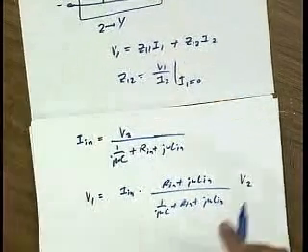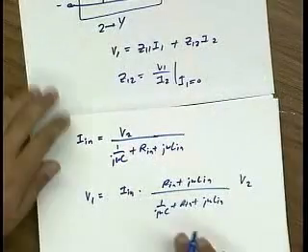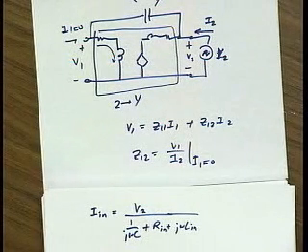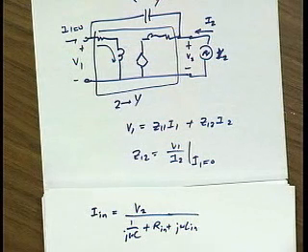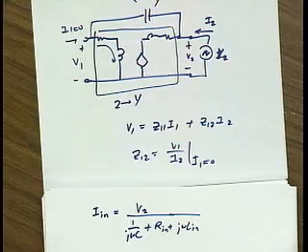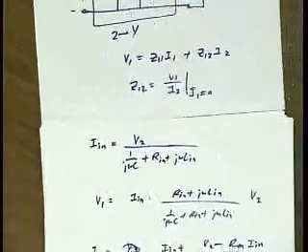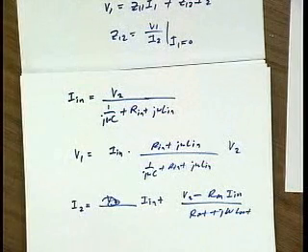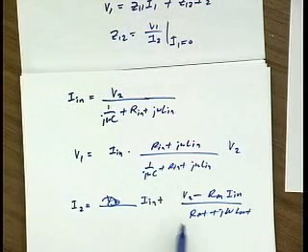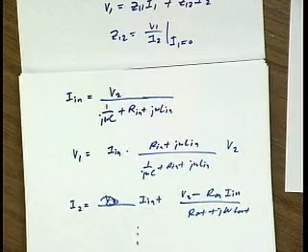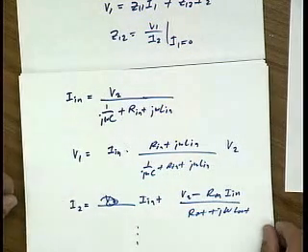Okay? So now I need to find the relationship between V2 and I2, right? So now I can say that I2 is equal to In plus V2 minus Rn In, divided by R out plus j omega L out, right? And I have an expression for In, so I can basically substitute and find the relationship between V2 and I2. Okay? And I won't do the algebra because I think you can all finish it from here. Okay?